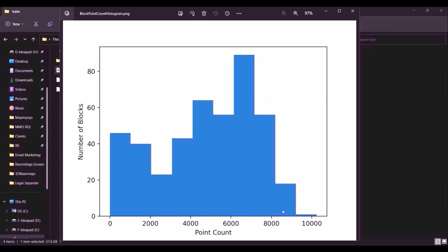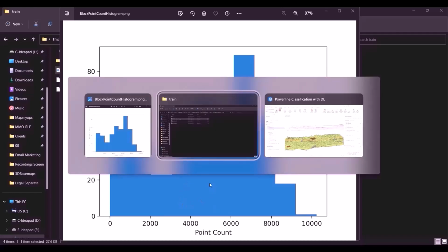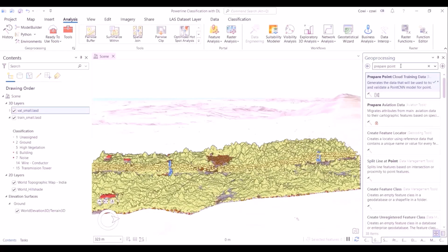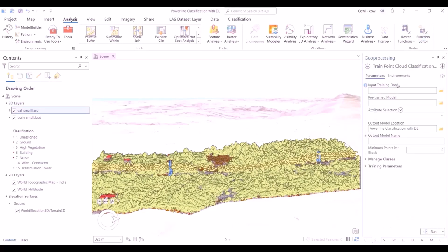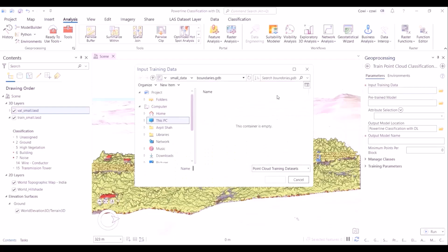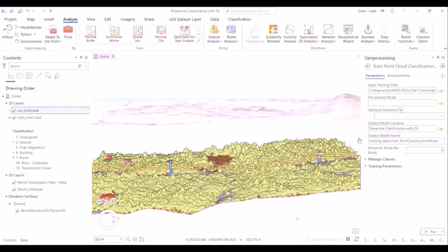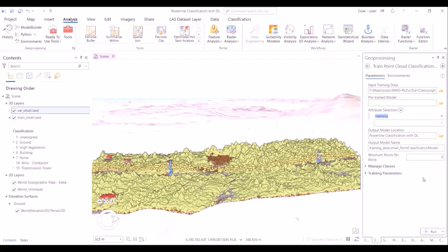The histogram output helps us to examine whether the number of LiDAR points within each block is sufficient or not. If it isn't, then we run the risk called subsampling, which distorts the classification algorithm's effectiveness. Because there are sufficient LiDAR points within each block, that essentially tells us that we can accurately detect the power lines from the particular block.